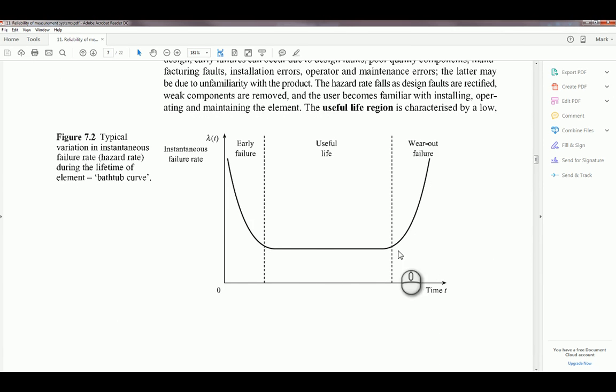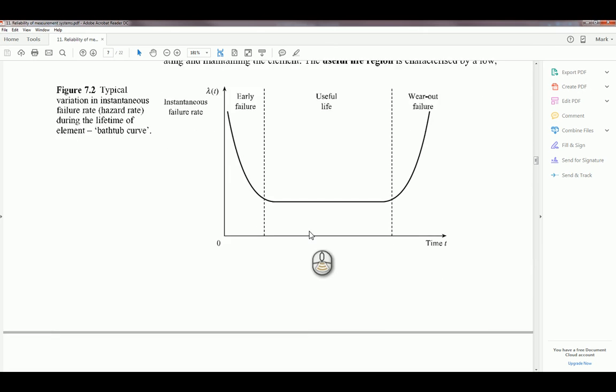We've got the wear out section and the bleed in, or early failure rate section, where it could be install times, commissioning times, delivery, all that would occur in that part of the life cycle. And then hopefully once it's installed and commissioned, you should be in around this area. It settles down and hopefully should be a linear useful life region of the sensor or measurement system, and then finally wear out.